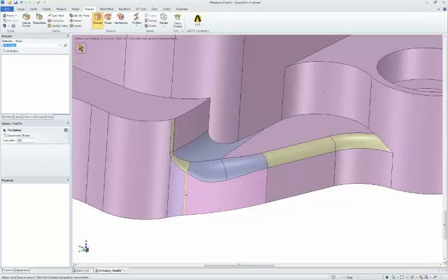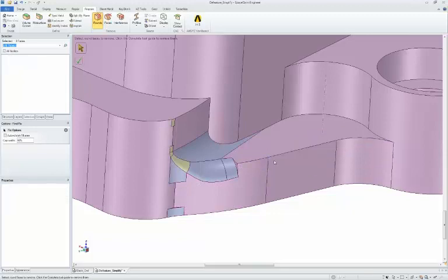Secondly, it might be hard to see on this model, but there are two pink lines hovering over the edge. Notice this is the length of the edge that I have. What this does is actually slice and subdivide these rounds for you, making it easy to remove and fill just one area, one section of a round at a time.